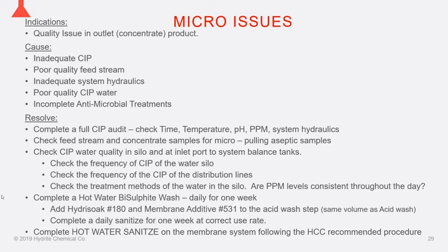So I remember distinctly a case where I went into a place and they thought they had a significant micro issue. They were getting ready to swap out all of their membranes, and one of the recommendations that we gave them was just clean out your sample ports. And funny, their micro issue completely disappeared as soon as they cleaned out their sample ports.